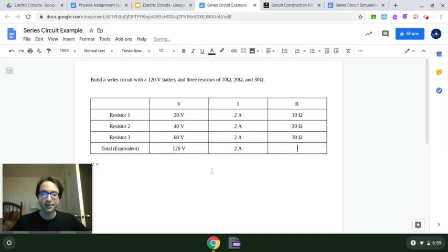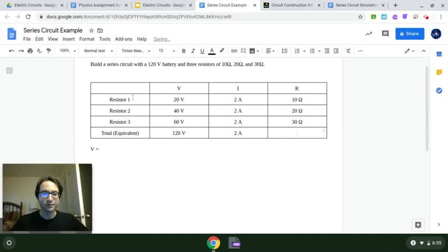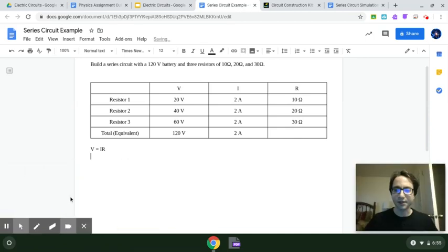Well, something else we need to keep in mind is that we already studied Ohm's law. Every component of this circuit needs to follow Ohm's law. Remember, Ohm's law is V equals I times R. Or you can think about it in terms of current. In that case, you're doing I equals V over R. Or if you want to think of it in terms of resistance, that means resistance of any one place in the circuit must equal the voltage divided by the current.